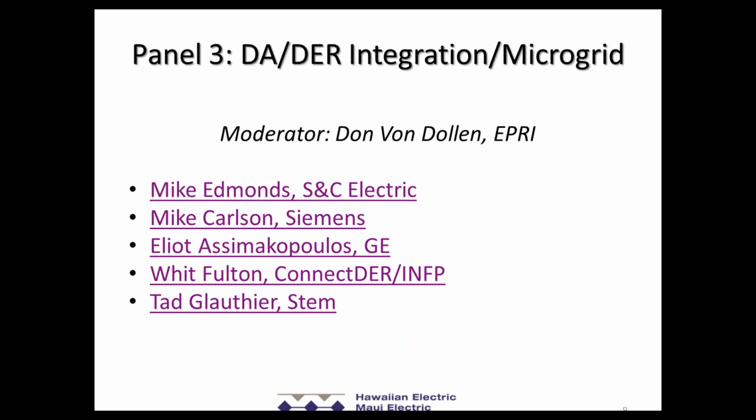As the infinite bus gets less infinite, how are you dealing with protection issues, namely ground fault current changes due to less generation on the system? Or will the DER systems be able to provide you the ground fault current that, let's say, a power plant for the infinite bus used to provide? I ask this because, as a utility owner, we are dealing with protection issues, and I'm wondering how you might be dealing with protection issues for microgrids or varying ground fault.